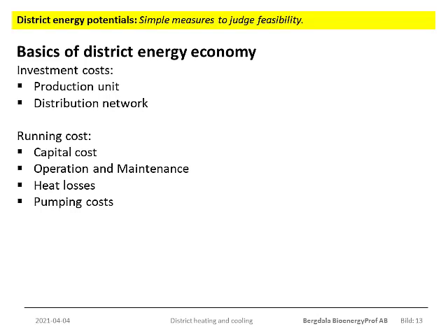Generally speaking, and simplified, may we say that the investment cost for the distribution network is linear with pipe diameter and linear with total length. It is also obvious that the heat losses and the pumping costs will both be strong functions of pipe diameter and total length of the system. So the mapping and design of the net is of paramount importance for the overall economy.